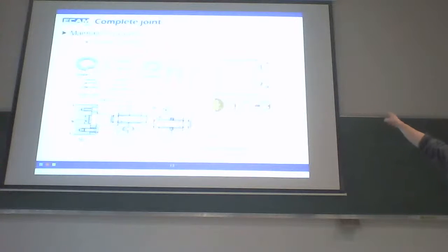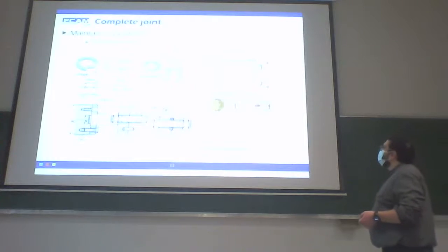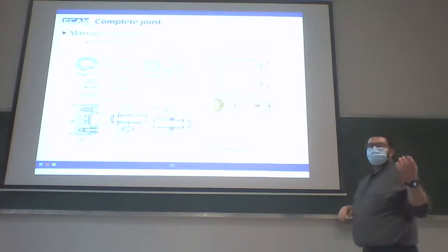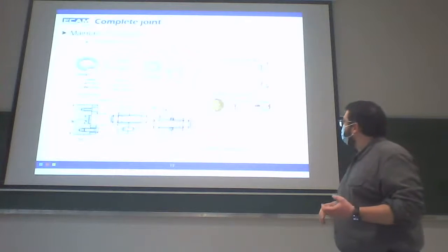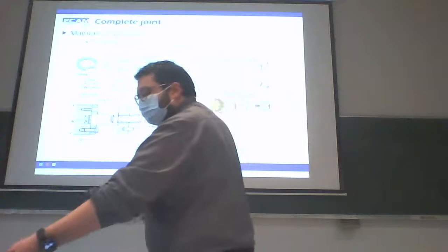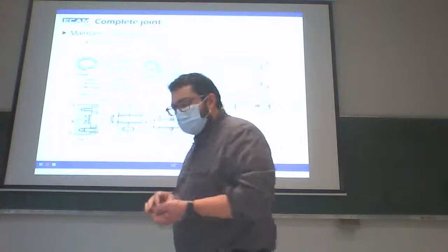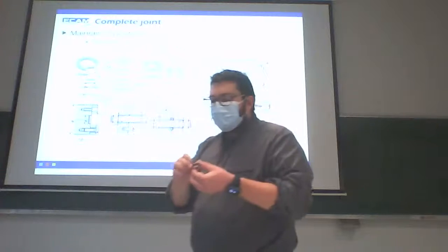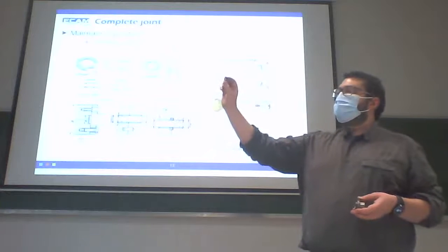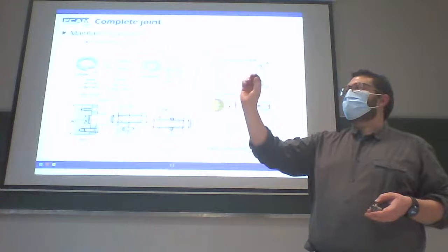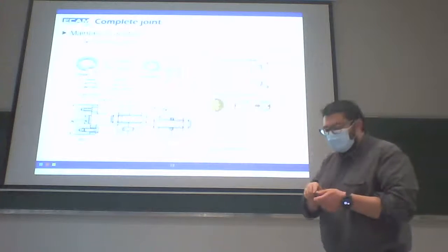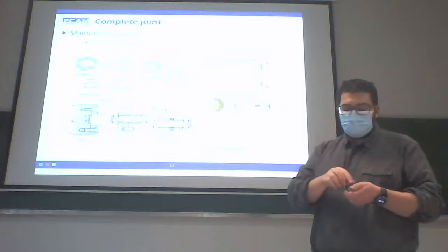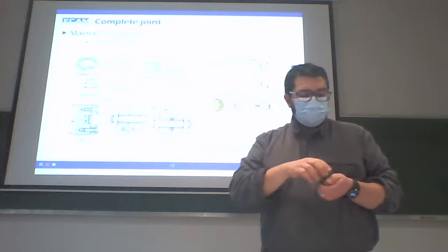Look at the technical drawing. Not always, but when using a ball bearing, we often use a lock nut. A lock nut is like this. If you only use the nut, it's a standard nut. But we will use the lock nut with a specific washer.